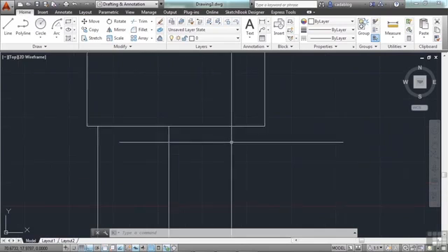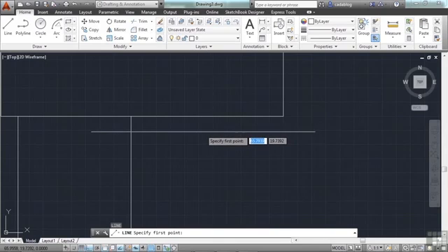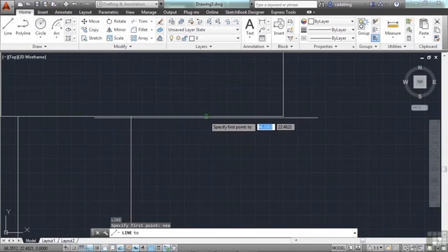Most homes have a door, and we'll draw it just so that the landscape architect knows where it is. Start your line command again. Type in NEA for the nearest OSNAP, or use the shift right click to bring up your shortcut window. Click somewhere on the house here.